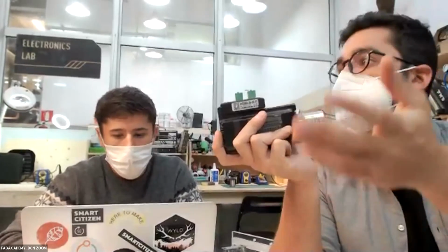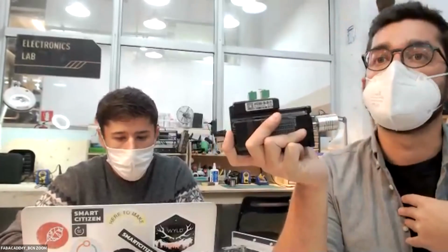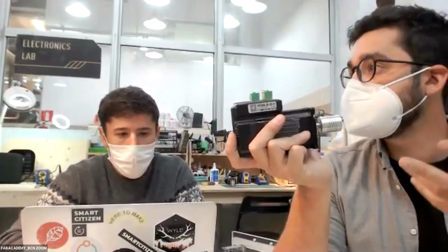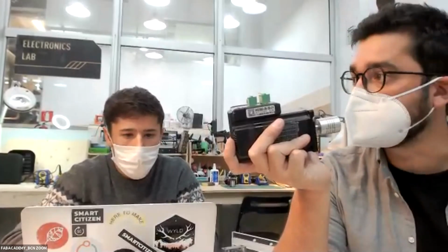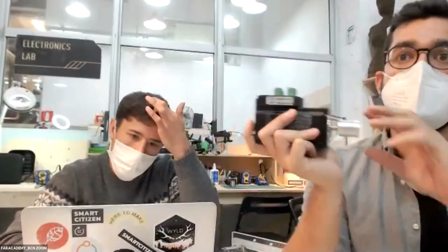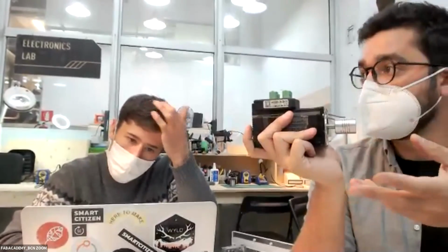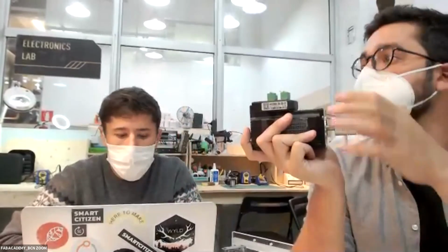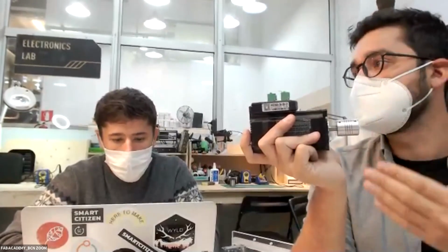We are giving the information on the amount of movement, and the motor is telling us if it has actually moved. Obviously, that is a way better system because we always have control of what we are doing. If the motor has not moved to the right position, it will still try to reach that position because it has not reached the target. So it's actively tracking the position until it finishes.